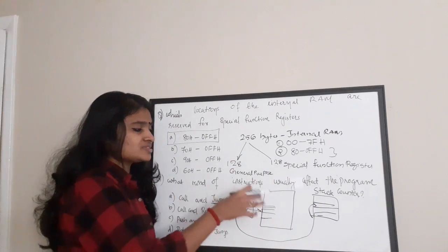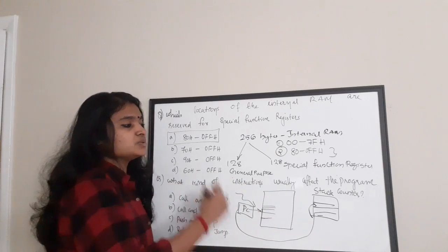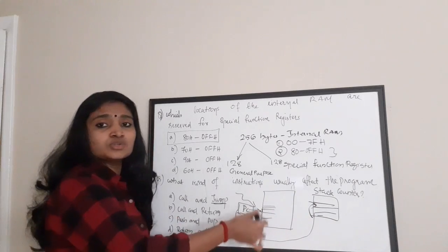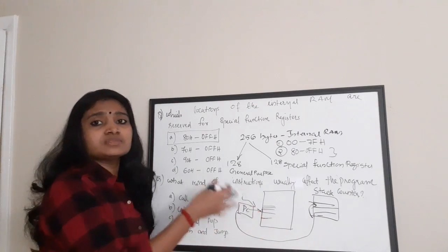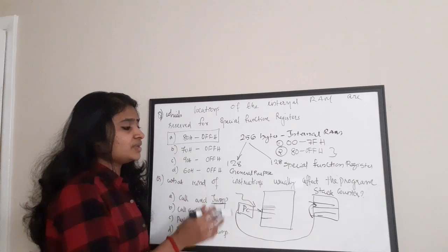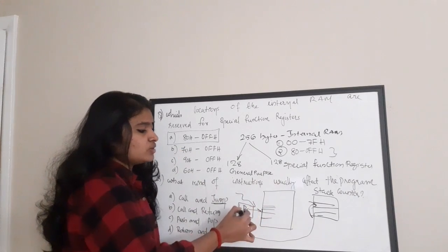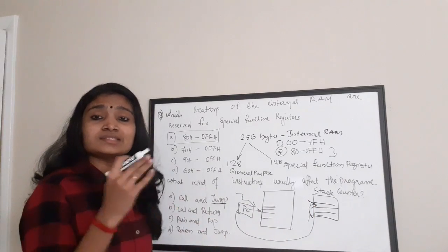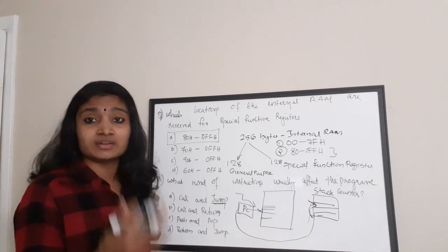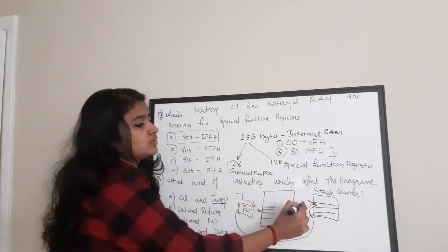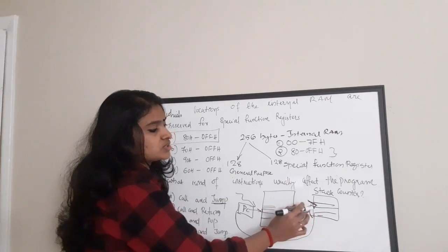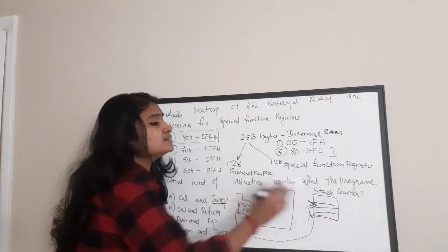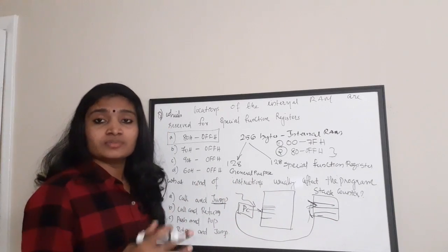So when the interrupt processing is complete, what will the processor do? It will go and take back this address from the stack and will continue the execution of the rest of the main program's instructions. So this moving of the program counter to the stack is called push, or inserting any element to the stack in general is called push. Here, when we are inserting a program counter address, it is actually a push.